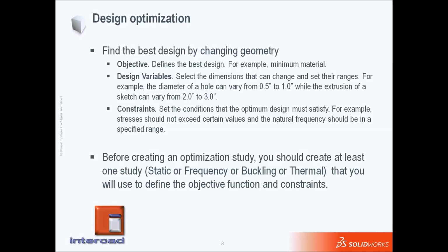In the case of a feature, it could be the sketch dimensions or the extrusion or cut extrusion or any other parameters we basically can find in SolidWorks. And the constraint here is not just for monitoring. We can set limiting conditions on this constraint. For instance, we would like the maximum stress to stay at a certain value and not exceed that. You will tell the software, this is what you're working with, this is the limitation you have, and the goal is to reduce the mass, and let me know what the optimum is.